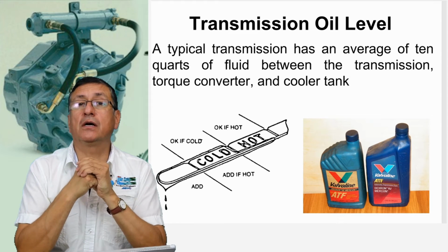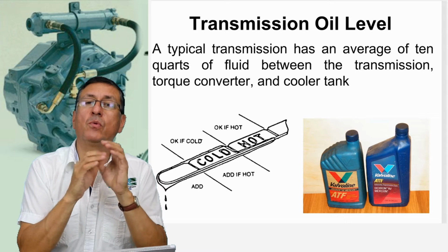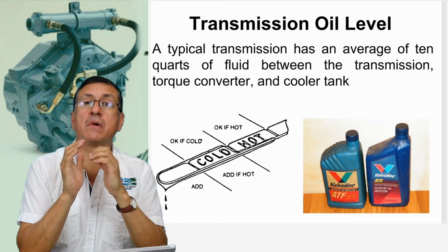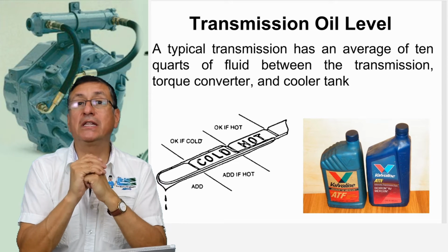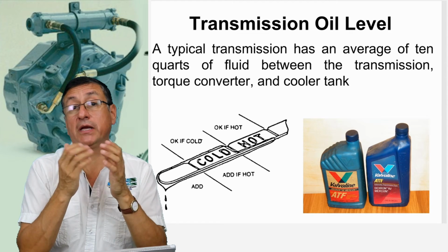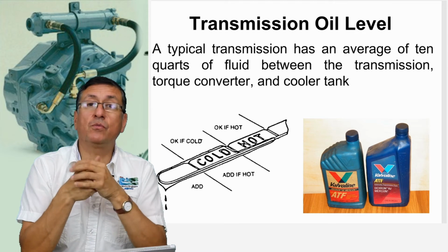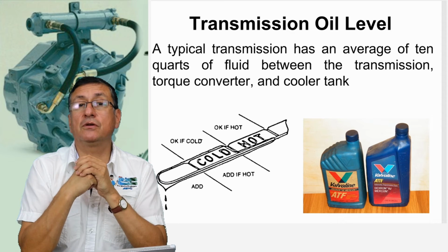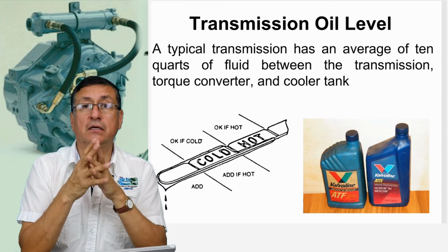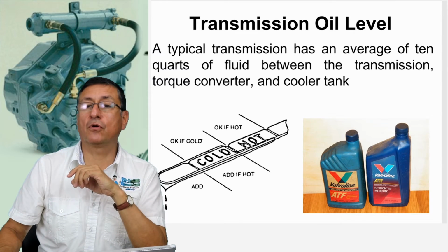Another important thing is that hydraulic oil expands with the temperature, of course. For that reason, when you remove the dipstick, there are two marks. One mark when the oil is cold, and another mark when the temperature of the fluid is hot. And you need to be careful where the level of the fluid is located according to the temperature of the transmission. The temperature of the transmission affects the performance of the transmission, of course.